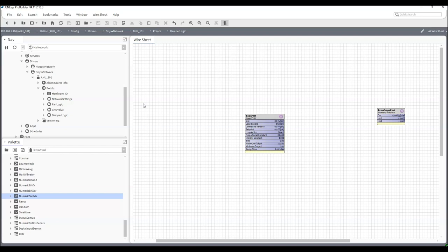Now, you may ask, why not night setup? Because typically it is assumed that night setup, the only way the building is going to get too hot is if we are in the summer season and there's no cooling there. So normally in night setup, you're not going to use the damper because if we are in the wintertime, you most likely will have a night heating rather than a night cooling.